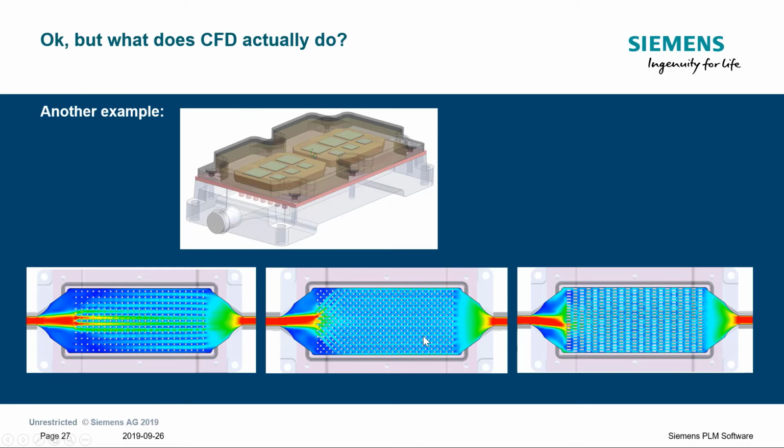How many do you need? How big should be the difference? How thick can you make them? How long should they be? There's so many possible parameters that you can vary. Or your experience probably didn't tell you anything about that pocket area here, where you could implement some guide vanes to spread the flow more, making use of the first few pins here where there's currently low velocity.